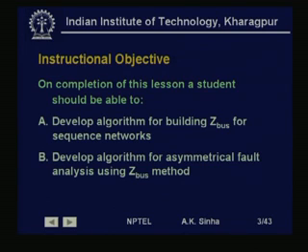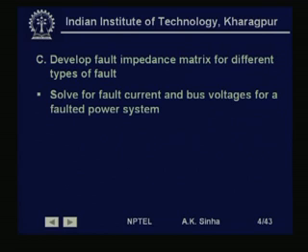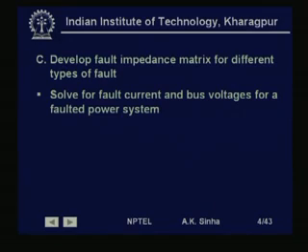Well, on completion of this lesson, you should be able to develop an algorithm for building Z-bus for sequence networks. You should be able to develop an algorithm for asymmetrical fault analysis using the Z-bus method, and you should be able to find the fault impedance matrix for different types of faults, and finally should be able to solve for fault currents and bus voltages for any power system for any type of fault, that means symmetrical as well as asymmetrical faults.